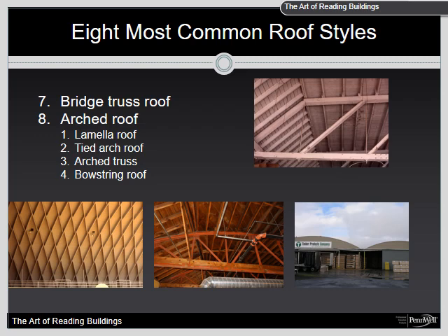Strength. Bridge truss roofs are well constructed and are easily identified by their characteristic sloping sides and ends. When exposed to fire, early collapse of main structural members should not be an initial concern. In most cases, the bridge truss will sag prior to its collapse. In fact, there are many examples of bridge trusses still standing, even though the rafters and sheeting are totally consumed.